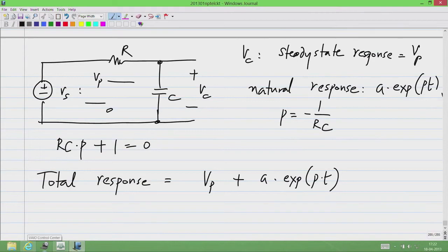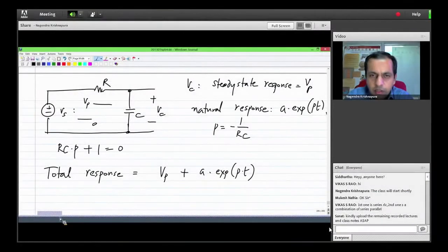There is a question which asks whether the characteristic frequency says something about the damping of the signal. Now, we will talk about that later. We did not introduce the term damping factor. Now, it turns out that if the characteristic frequencies are both real and negative, you will have an overdamped system. If they are identical, it is a critically damped system, and otherwise it is an underdamped system. But we will come to that in the next lecture.